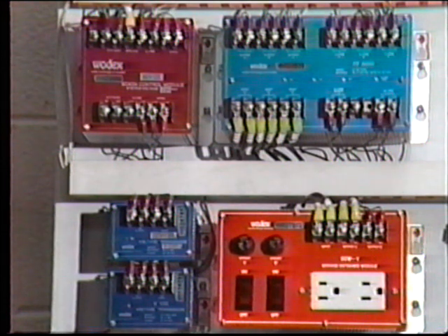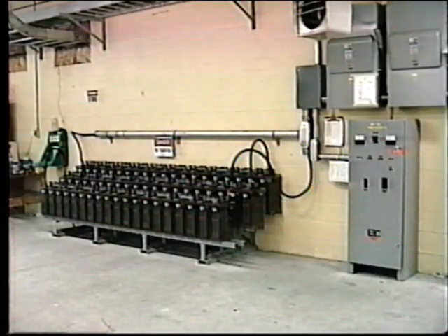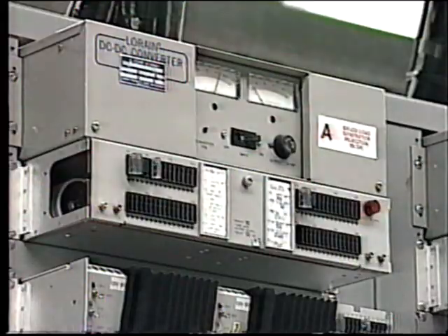Generally, the transducer cabinet requires a source of power for operation of the transducers. This supply should, of course, be a non-interruptible power source, similar to that for the RTU. The RTU itself is usually powered from the substation battery, which is normally 48-volt or perhaps 125-volt DC, floating on a continuous charger. A DC to DC converter is used to provide the specific voltage required for different RTU components. This also provides isolation from any spikes that may appear on the battery voltage from the charger.